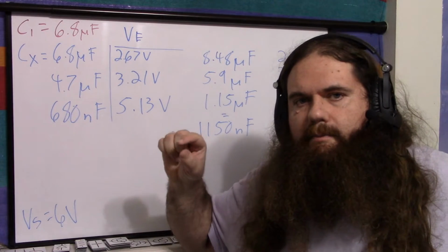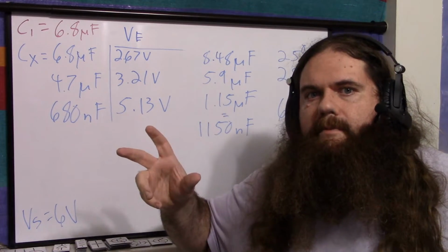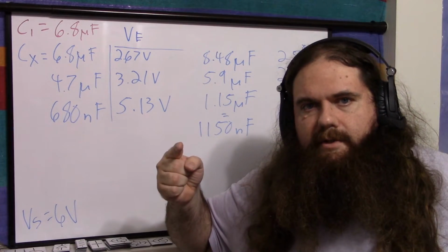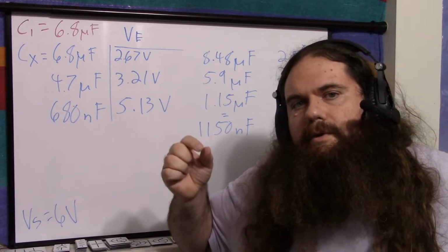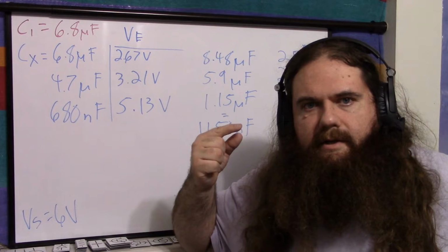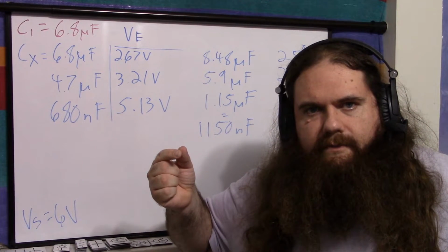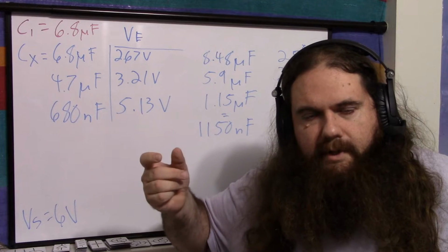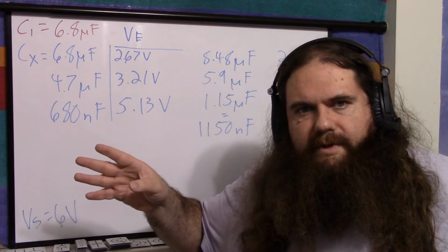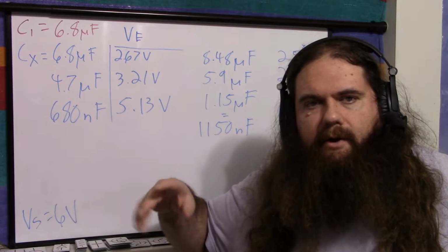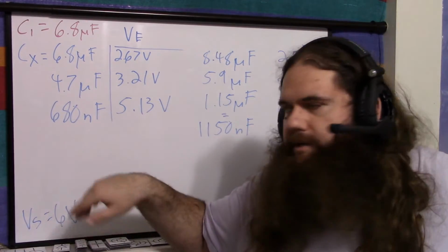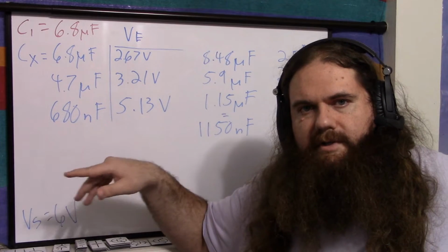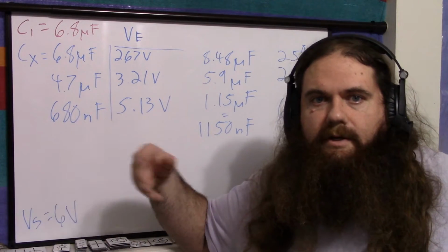Because the errors are compounding by doing math on them. When you measure the voltage, you've got a variance in one capacitor, a variance in the other capacitor. We're assuming that the actual losses, like the input bias current of the op-amp, are minimal. The losses to resistances of wires is minimal. My power supply is reasonably accurate. All those losses are small enough that we ignore them until we get down to like the small single-digit nanofarads, at which point you need better equipment.